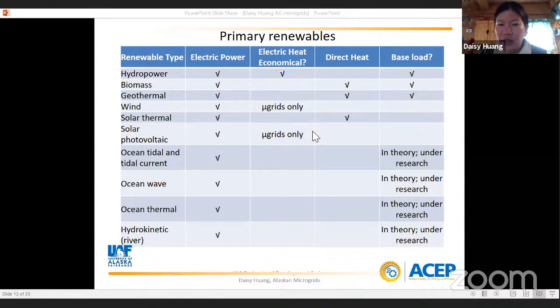And there are different ways to do that. The turbine manufacturers have ways to do that. Some of them are mechanical, like you actually rotate the blades to cut the angle of attack, and then it'll spin slower and you'll generate less electricity. Another way is to put a brake on the wind turbine and it'll spin slower. Or you can do it electronically, just accept less power and blow off the power. Or just dump it on a load bank, attach a big toaster to the wind turbine, and have it heat that instead of dumping that excess energy on your grid. And solar, the same thing. You can curtail solar production when it's making more than you need.